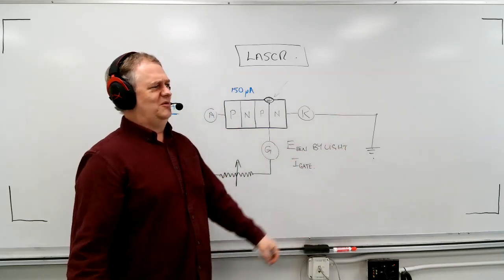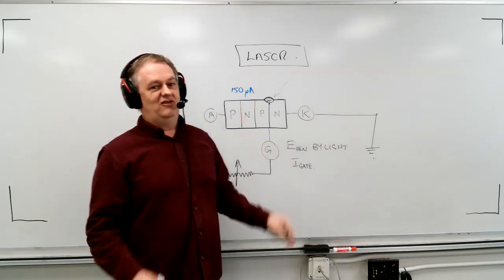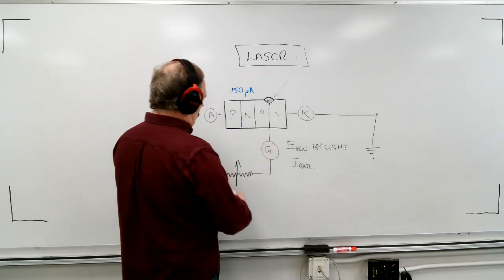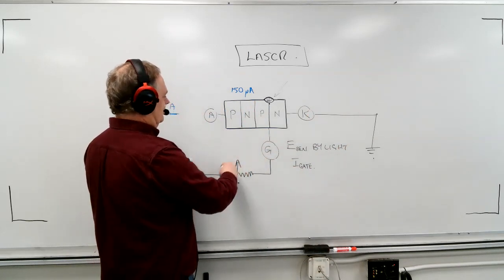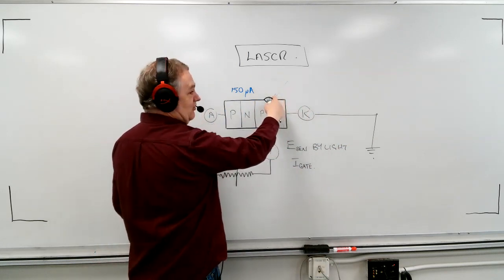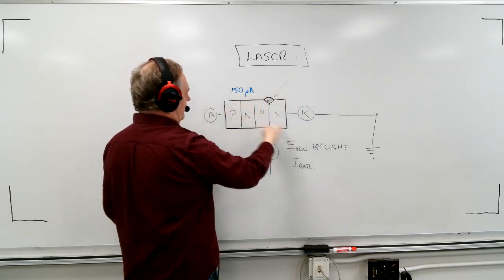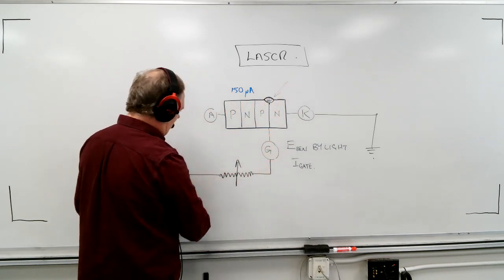You go, whoa, it's still almost black. Like it's just a little tiny bit of light on the horizon. I don't want the lights to go off yet. So here's what they do. They say, okay, what we'll do is we're gonna set this resistance to a very low level. And now what will happen is when the first light appears here, let's say that it makes 200 microamps. Well, almost all of it drains off through this resistor to ground.